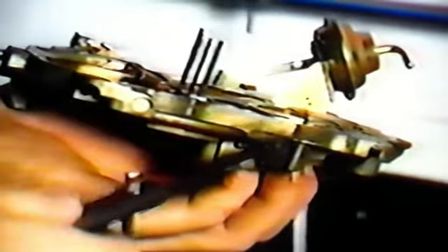When removing the air horn, be careful not to damage the gasket. One safety tip is to use a small straight edge to hold the gasket down on the bowl as the air horn is gently taken off. This not only keeps the gasket in good shape, but should also save you from having to replace it. As the air horn is lifted off, you'll notice this small pin or finger. When it is in place, it touches the TPS and positions it for making necessary adjustments. To prevent damage and aid assembly later, we found it helpful to back out the TPS screw until the pin is flush with the air horn.